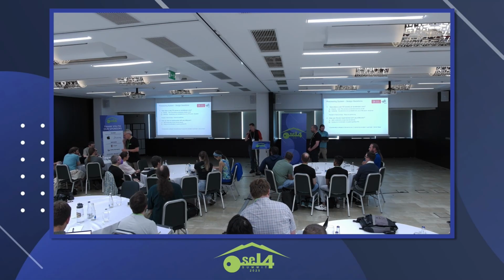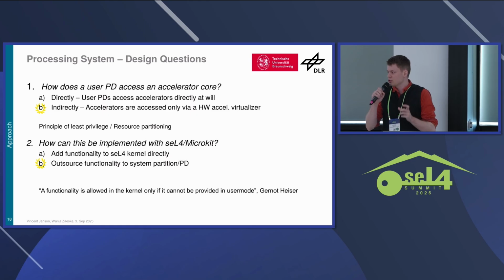That's an excellent question. The answer is you need to make sure that you know when these transfers are happening, and you have to provide empirical data to show that the transfers are not hurting the real-time performance of your application in an unacceptable way. The state of multi-core interference in certification, to which I would claim this to be a sub-problem, however, is kind of dire. And there have been maybe 2 to 3 certification programs going on since the early 2020s that actually succeeded in this. So this is a question that is not definitively answered, and we are unhappy with the answers we have so far.